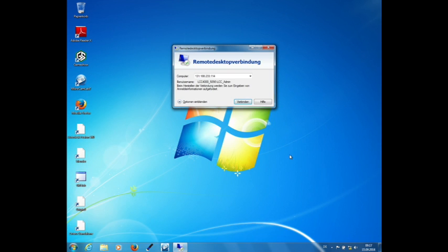It's actually just a screw that we can adjust that will give you whatever vacuum level we want. But if you change it, over time the vacuum level will change, because inevitably you will add contamination into the vacuum. Then you can do something like a mini bake.